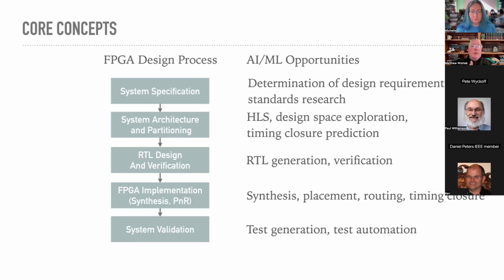As we go into system architecture and partitioning, there's a couple of key things here. One is, there's a high level synthesis paradigm, but it's really difficult to implement in practice because you have to tell the tools how to take that high level design in C or SystemC or C++, whatever language you're using, and help guide it into doing a reasonable RTL design.